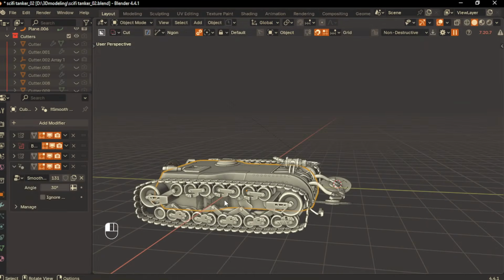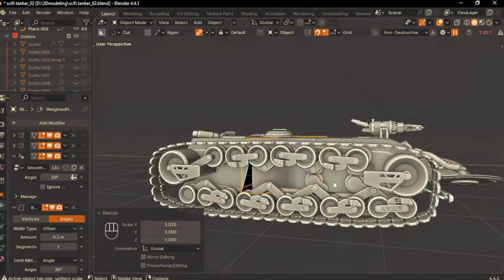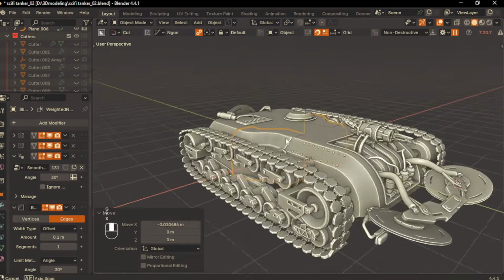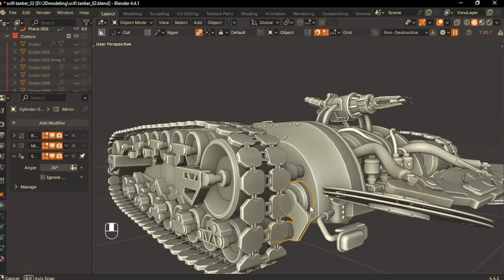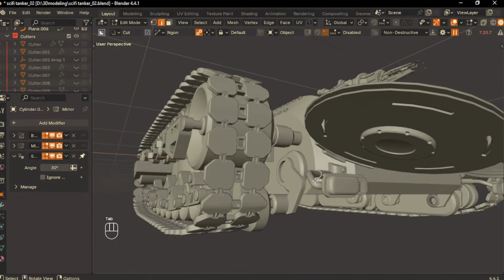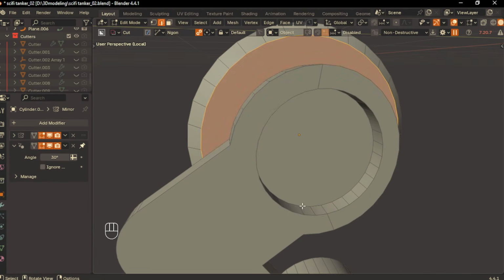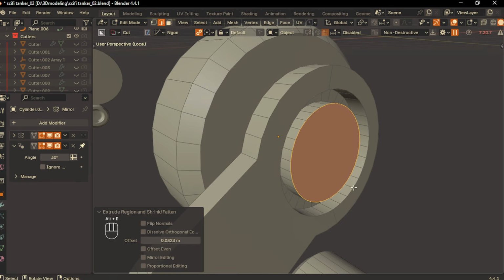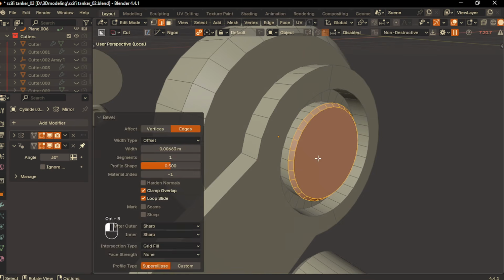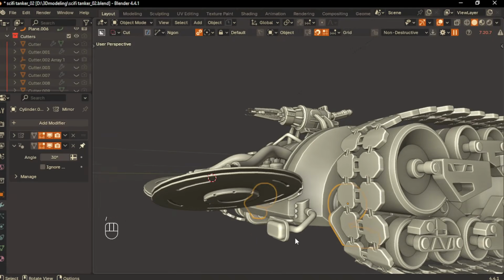Now, I notice a small issue with the armor shield. It's slightly overlapping with the geometry. So, let's extend its size on the X just a little to fix that. Next, on the bottom connector, I'm going to apply the smart apply and go to edge mode. Let me activate this piece, switch to face mode, select this inside face and insert it slightly. Then extrude it out and run a small chamfer along the face. That should give it a cleaner and more refined look.